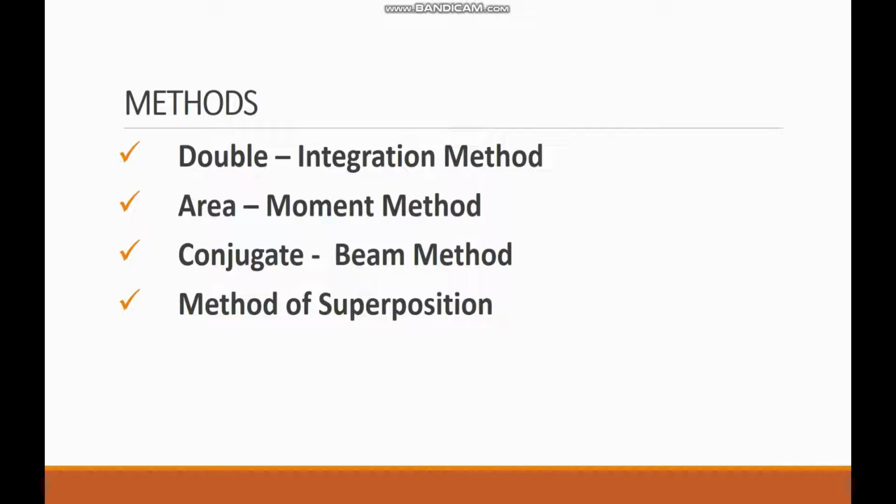So the common basis of these four methods is the differential equation that relates the deflection to the bending moment. They are based on the same principles, but they differ in techniques. Beams are frequently governed by rigidity rather than the strength. That's why building codes specify limits on deflections as well as the stresses. Excessive deflection of a beam is not only visually disturbing but may cause damage to other parts of the building. For this reason, the building codes limit the maximum deflection of a beam to about 1/360 of its length.